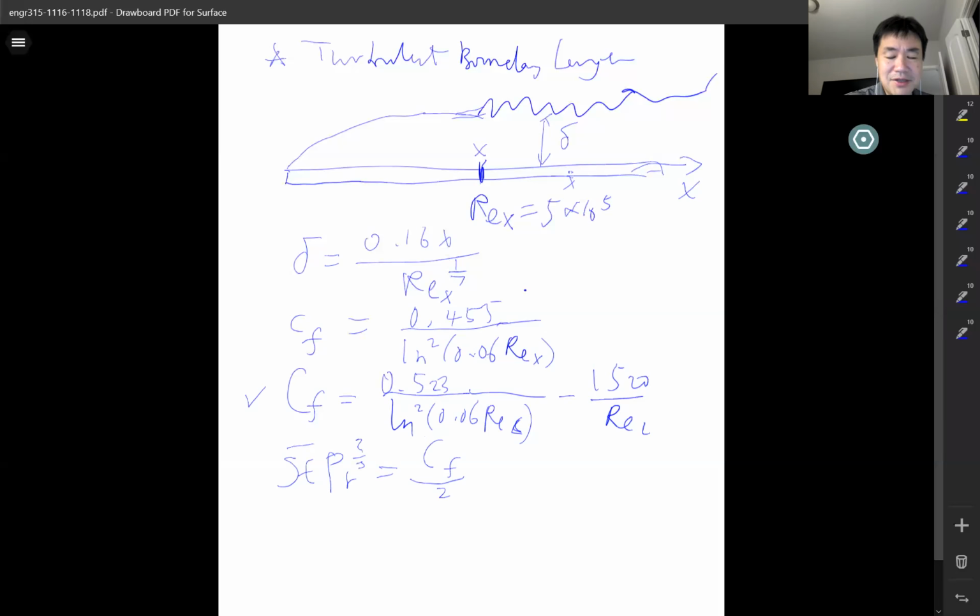This is the Reynolds analogy we showed you last class for the laminar boundary layer, but here it still stands. So based on the relationship between CF and the Reynolds number, you can have another correlation to find out the Nusselt number. Obviously the Stanton number has the h there, and the CF has a Reynolds number there.